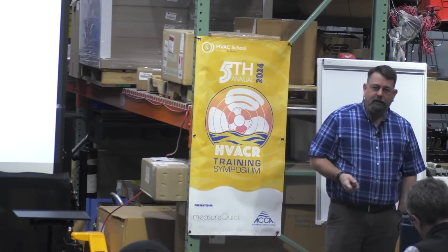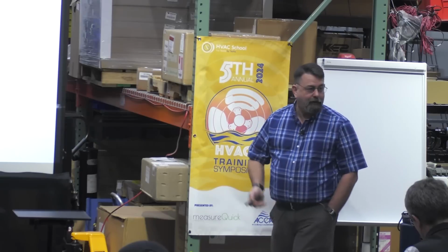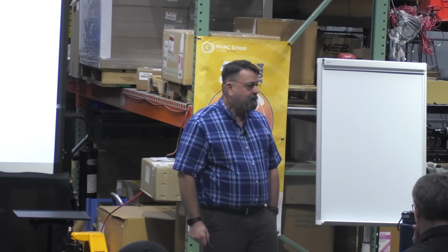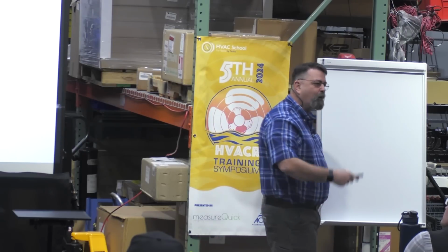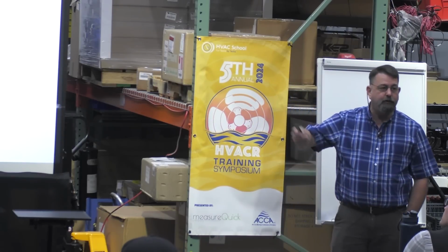Well, is that not what I need? That and the refrigerant type and a PT chart, I can calculate superheat, right? So I'm going to be checking that. That's what that snow means: hey, walk over to the controller, hit a couple buttons, make sure you're all right, right? If it was flooding, what would it look like? That, right? I can't tell the difference, is my point. I've got to go look at my superheat and know.